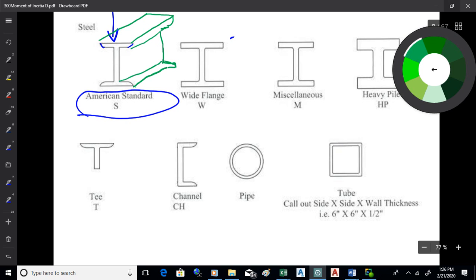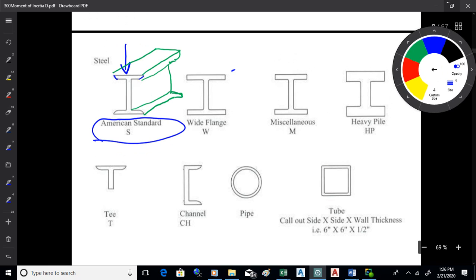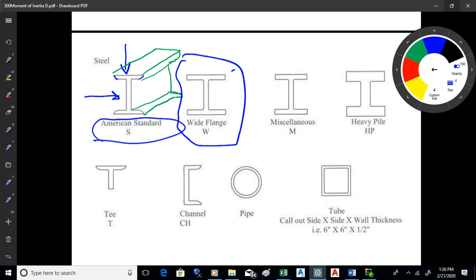Yeah, okay. So American standards work fine in a vertical load, but the problem is when you start loading them from the side, they're weak, okay? They don't handle that very well. Now, why would I care about sideways loads if I'm making a building or something? Yeah, earthquakes, lateral loads, okay? So, especially in this part of the country, we care a lot about that, okay? So, what they've evolved to now, most beams are now a wide flange. They're squared, they're a little stronger flanges, and they're wider. They resist what I call lateral side loads better, okay?